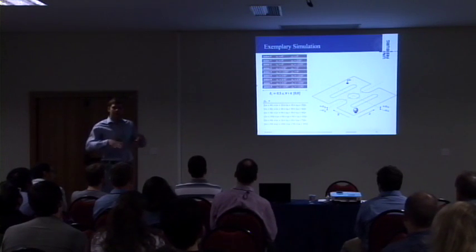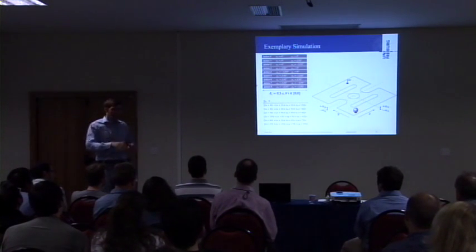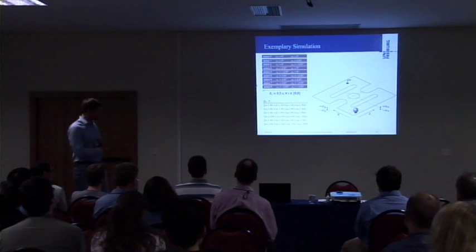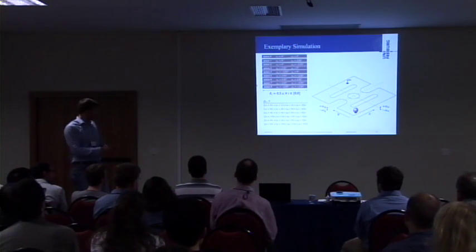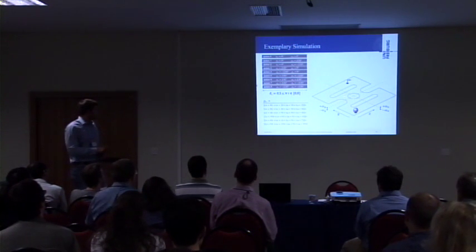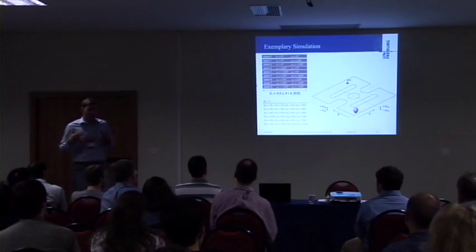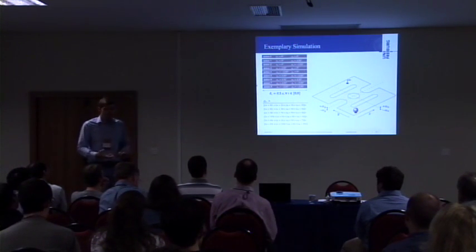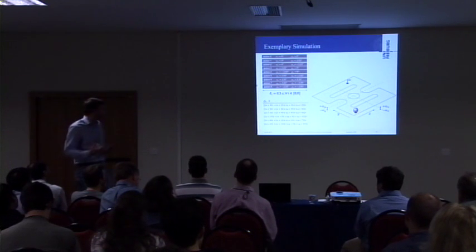Therefore we can incline the plate around 2 axes, leading to 9 different plate inclinations, each having a duration delta I of half a second. The holes and the edges of the plate are simply modeled by preconditions, so we check in each state if we have fallen into a hole, and if not, we can continue with the planning process.